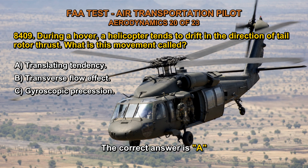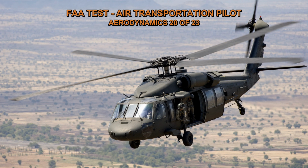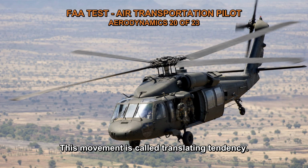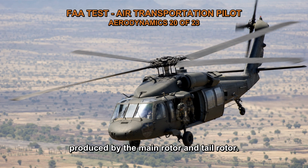The correct answer is A. During a hover, a helicopter tends to drift in the direction of the tail rotor thrust. This movement is called translating tendency. Translating tendency occurs due to the asymmetrical thrust produced by the main rotor and tail rotor.